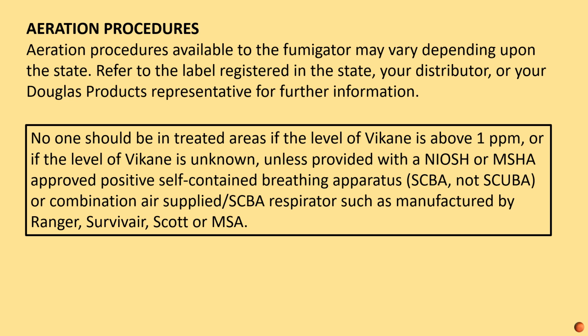No one should be in treated areas if the level of Vikane is above 1 part per million or if the level of Vikane is unknown, unless provided with a NIOSH or MSHA approved positive pressure self-contained breathing apparatus, SCBA, not SCUBA, or combination air supplied SCBA respirators such as those manufactured by Ranger, Survivor, Scott, or MSA.